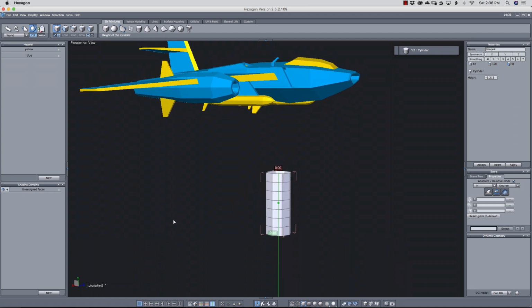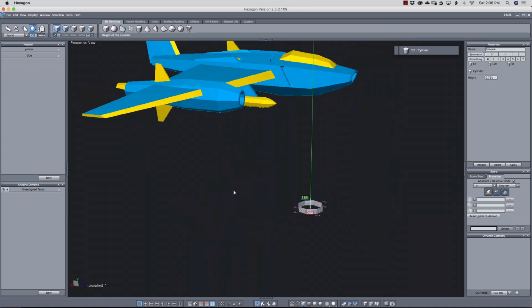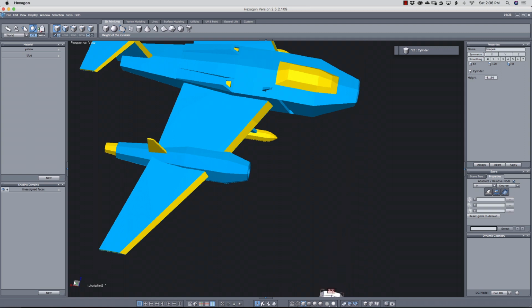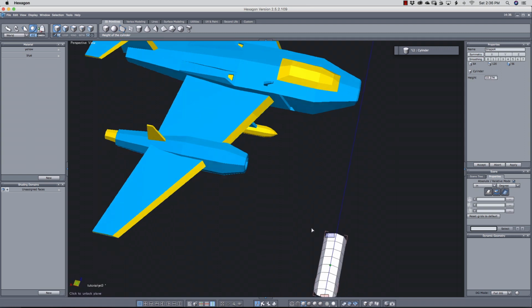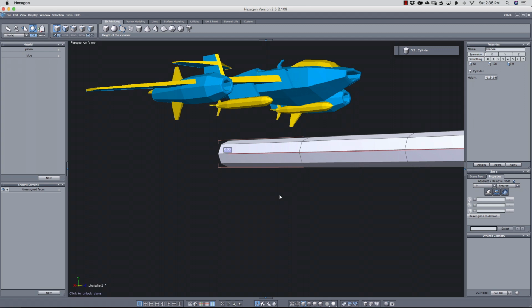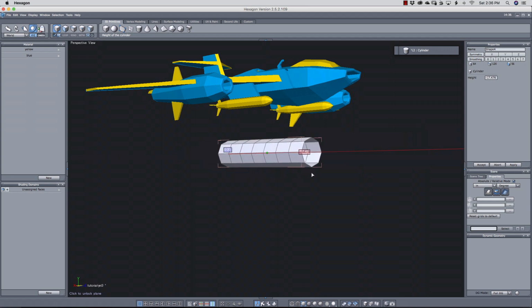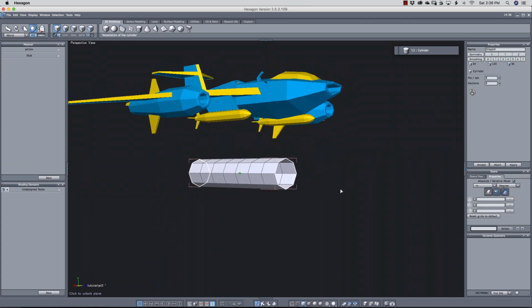This isn't a big problem, but the cylinder wants to draw in an up or down direction. We want to change that. I can pivot the view to the Y plane and then click this to activate it. It's now yellow, showing it's active. And now our cylinder will draw in the direction I want. All we need to do is orient the view in that direction.